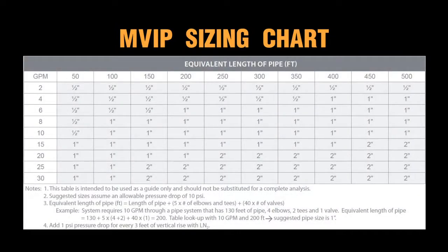Utilizing the sizing chart will help determine pipe sizes required. Typically, a main header supply is designed with runs off of the main header. These runs typically are sized down 1 diameter from the main header. Each branch from the run is typically also reduced 1 diameter from the run. Drops from the runs are typically reduced to 1/2 inch diameter. Each system design may have unique circumstances that may require using what is not typical.